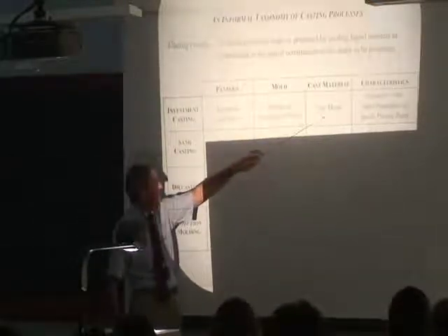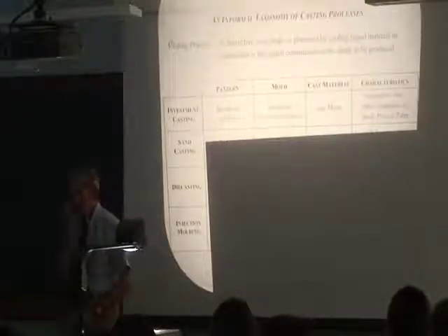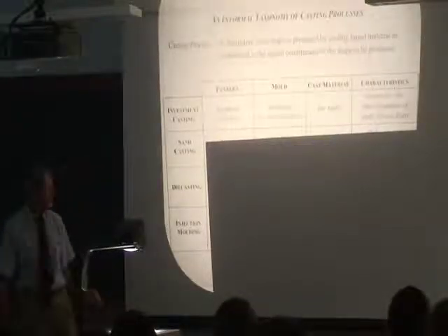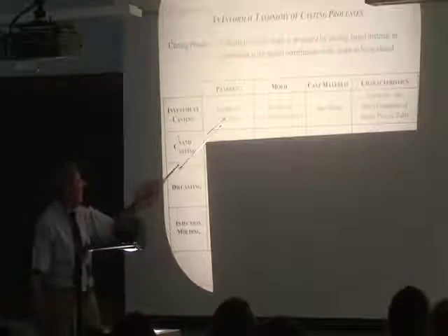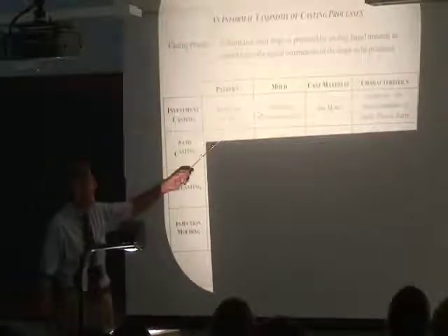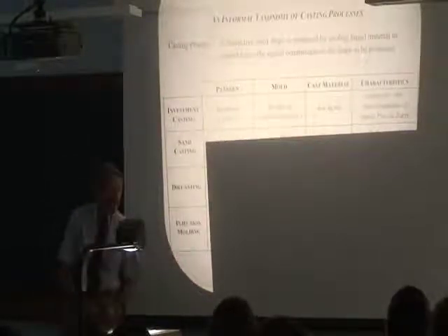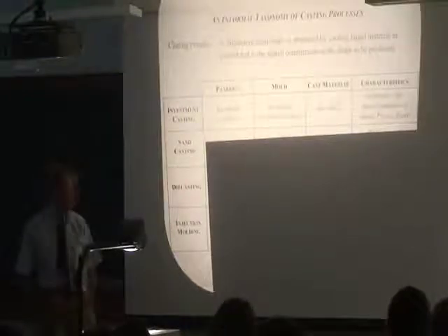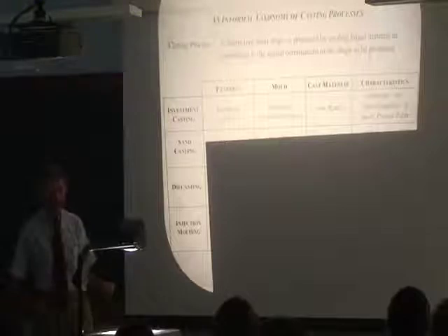And finally, you have this very precise part. So for every turbine blade in a gas turbine, or steam turbine, you start with a new pattern and you make a new mold and so on and so forth. That's why it's expensive. But it's precise and you can use it for very high temperature metals and so on.